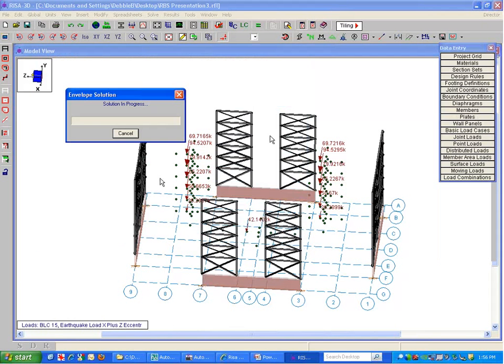And then sometimes some of these might change, and they are going to change, right? Because as the load gets distributed, where some place got stiffer, load got brought into another place, okay, and dragged through that rigid diaphragm a little bit differently. So this is an iterative solution. So what we'll do is we'll solve this one time, and then we'll take a look at the results, and we'll see what's happening. And if you notice, I do have P delta turned on, so it's doing my shear P deltas behind the scenes, so it takes just a second longer.